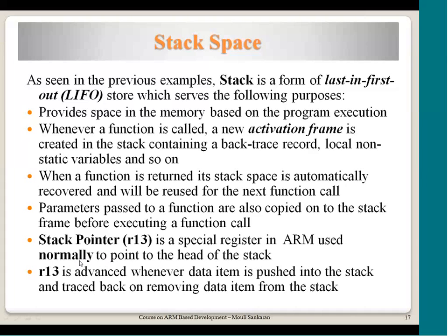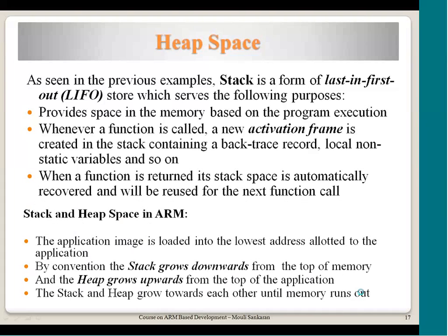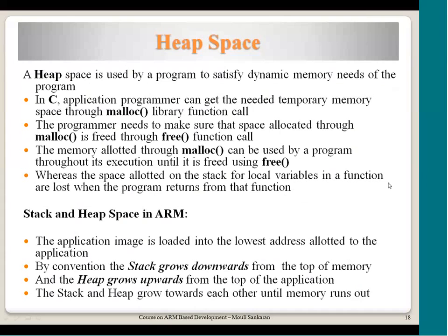And so R13 is used for the stack pointer here, and whenever a data item is pushed, R13 is incremented or decremented based on how the stack grows, and when the value is removed, R13 is adjusted back. Now we also have heap. This is the data area.